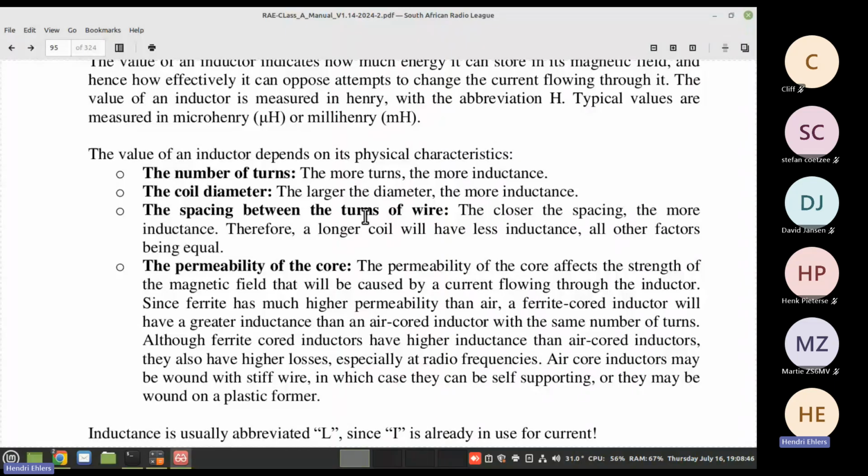So there you'll use a former to wind your coil. Webb made one antenna with a coil at the bottom out of stainless steel or spring steel, and that works. So they don't have a former, and that makes the antenna a lot cheaper than all the others that need the former, and it works just as well.